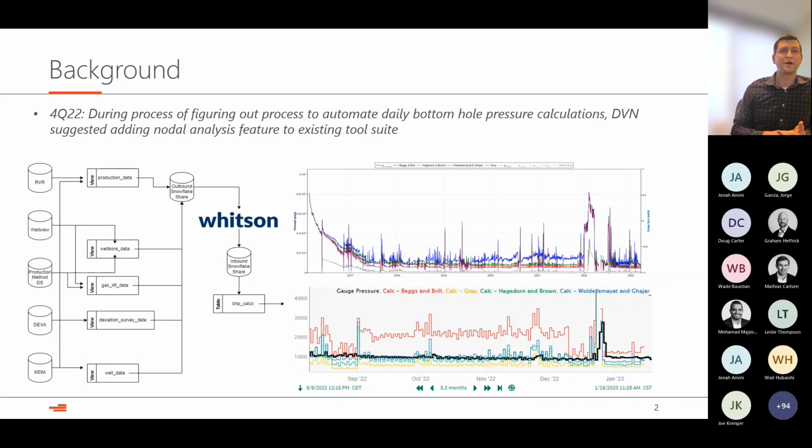that analysis work. So what we suggested was, hey, we're basically creating the wellbores. We're doing everything but grabbing a reservoir pressure and inputting a new tubing configuration. As Graham already mentioned, with their flowing material balance calculations, Whitson's solving that first problem for us, that reservoir pressure. And then the other one is just an input that we would need to create, which is the alternate tubing configuration that we would want to be installing into the well.